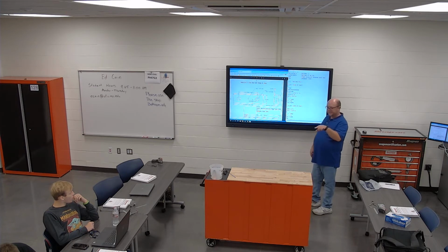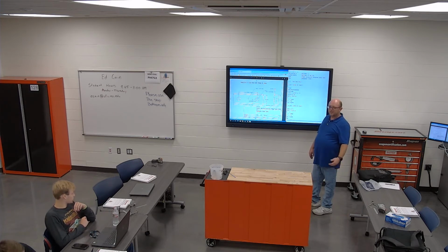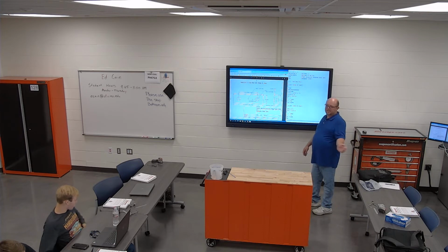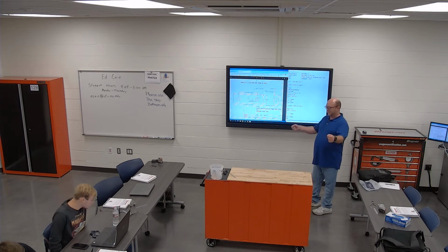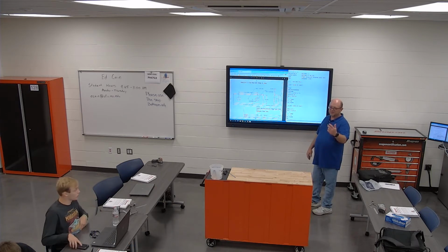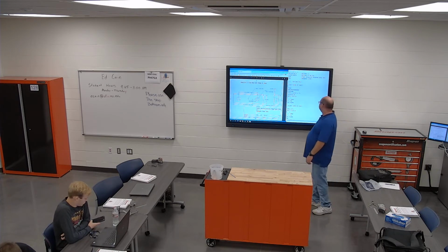Conventional milling you feed into the travel, so the cutter pulls the material, versus you pushing the tool against it. Yeah. Otherwise, your backlash will try to suck it into it. These machines aren't so bad, but I've seen some machines that you can take like this, and if you do that with one of them, your cutter explodes. Or you put it in the part otherwise. Yeah.